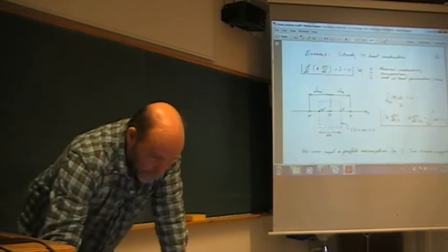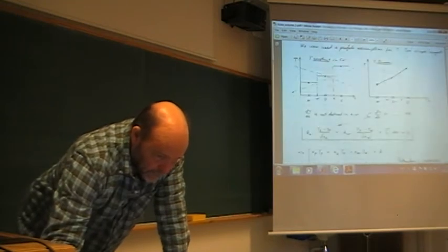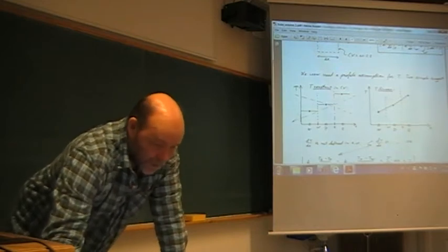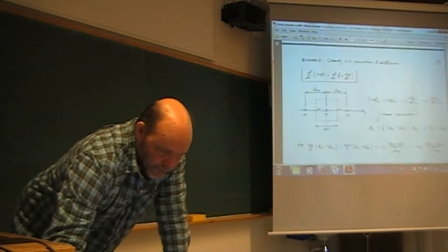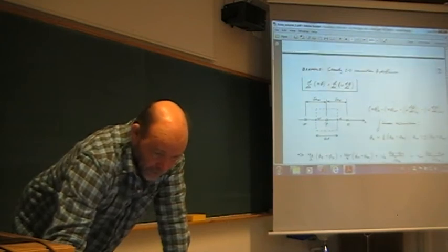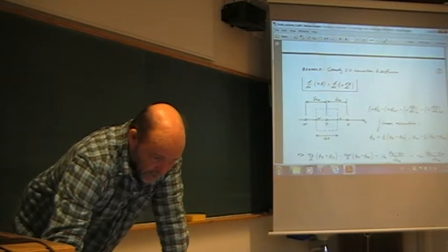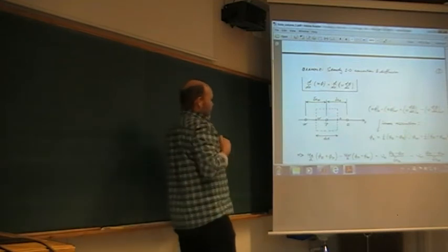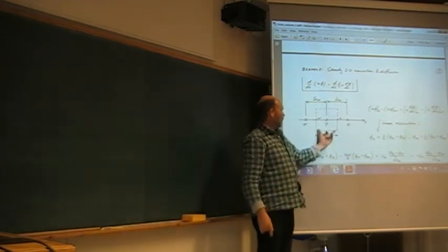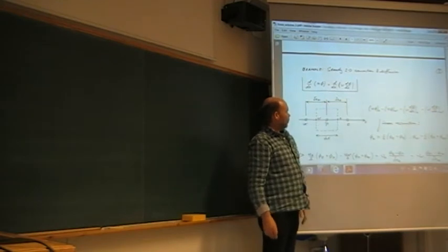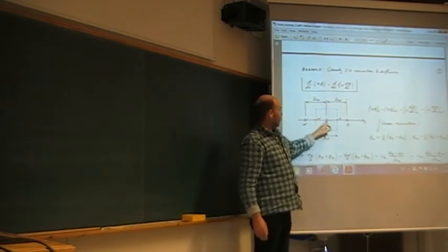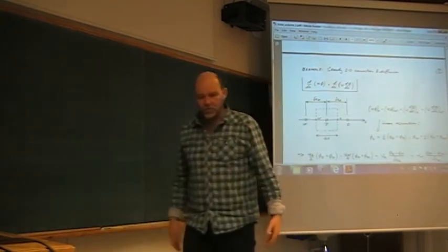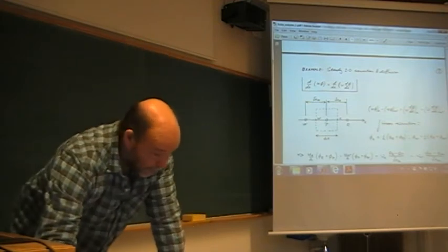We looked at a couple of examples, found out linear variation, that's okay. Then you will get the exact same discretization scheme as you would with finite difference if you have constant delta x. But here you will have better bookkeeping, you might say, with a lot of different delta x's here. So you can play around a lot with the location of your layout. It's on an integral version already, so you can do pretty much what you want here.